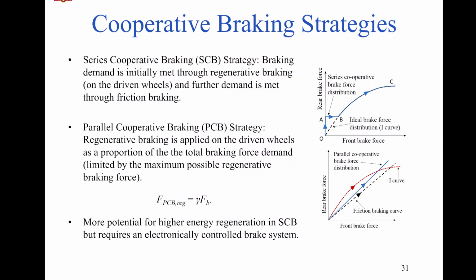The one benefit of a strong hybrid is that you do not require such a huge battery, because there is also an engine to support you. But in terms of cost, we are increasing the complexity of the system. A strong hybrid will have components of an electric vehicle as well as components of a conventional IC engine driven vehicle. Because of that, the complexity increases.